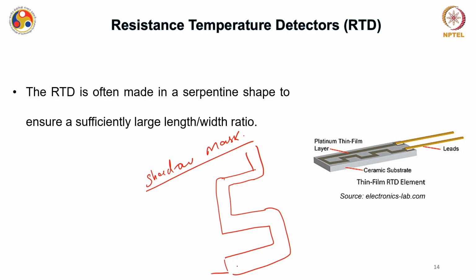Okay. And like in the thermal evaporator, for example, there are various methods of deposition of these materials. You have PVDs and you have CVDs, physical vapor deposition and chemical vapor deposition. Usually physical vapor deposition is the preferred method for depositing these materials. In fact, in microelectronics also people use physical vapor deposition to deposit metals for making contacts and for different interconnect applications. Okay. Now if you have this kind of shadow mask, please note that this area is hollow.